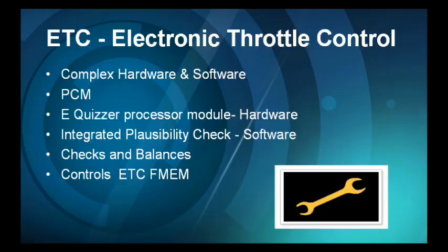Moving on to another important system in the Ford engine management system, electronic throttle control. We know that all manufacturers are embracing electronic throttle control. It yields many benefits to the manufacturer, such as torque management, no additional components for cruise control, better engine management. It's easy to come in and out of multiple displacement systems, such as displacement on demand or multiple displacement system. It really just helps all of the systems work together.